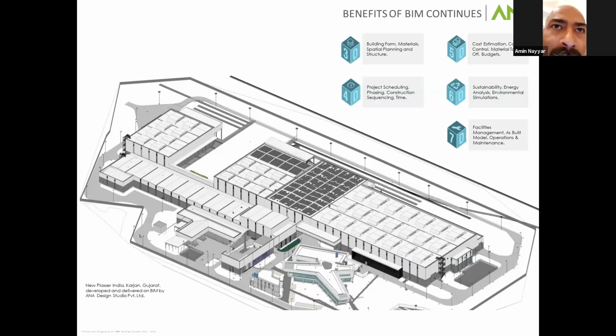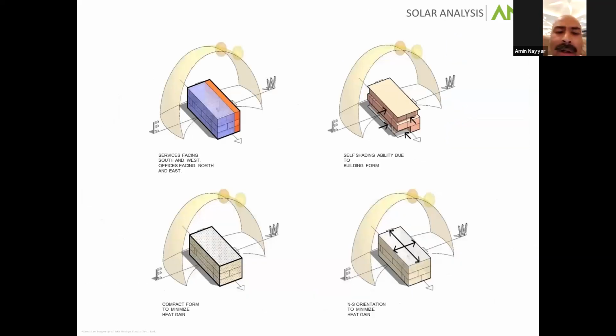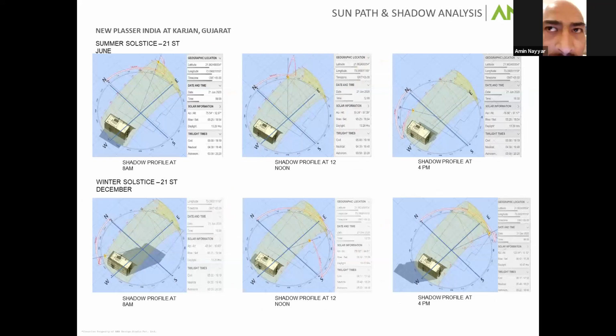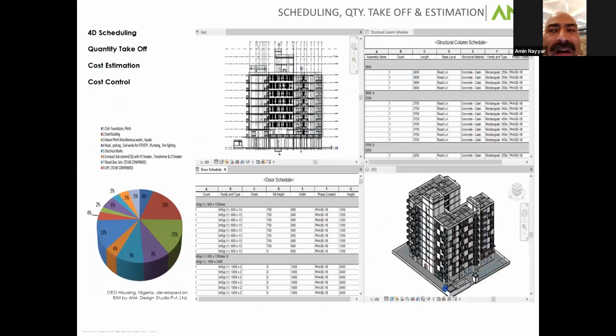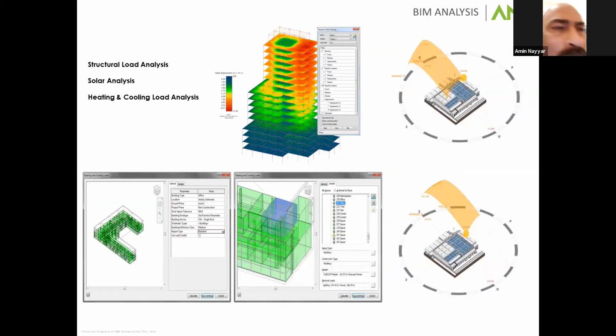As you can see, the building is very long, and we had close to about 400 meters of piping length available. So we simply embedded pipes in the foundation system at very little extra cost to the client. And we realized that the air that was going into these pipes and then eventually being thrown into the open spaces of the building was coming down by between 3 to 4 degrees Celsius at almost no cost. We had only just the cost of being able to suck in a certain number of cubic meters of air and then throw it into the building.